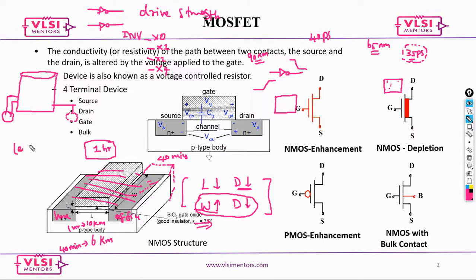Less load. Okay, you can use lower width, and if you have a bigger load, okay, lower width, less load, you can use lower width. Now say you have a bigger load, then you definitely need more width, more W. Okay, remember, this is just a concept. Now you understand it, and we will learn how to design a circuit with different drive strengths and all of that.